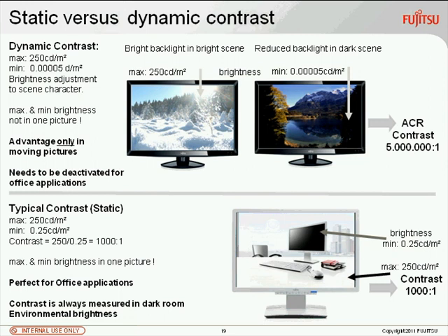The brightness of LED can be reduced almost to zero. In former times with CCFL, this was not possible. With CCFL, if you reduce it, there is a limit, and then it suddenly stops lighting. So with CCFL, the limit was a contrast of about 50,000 to 80,000 to 1.